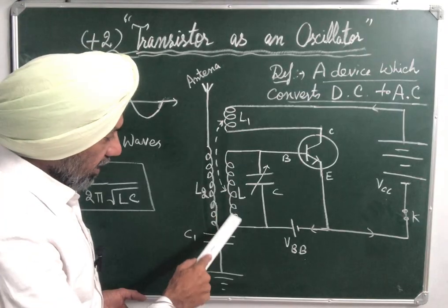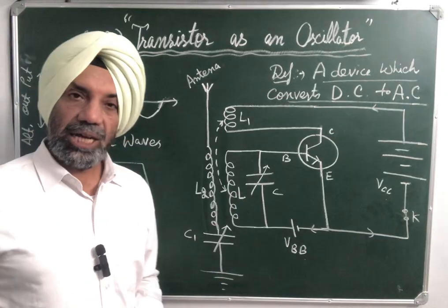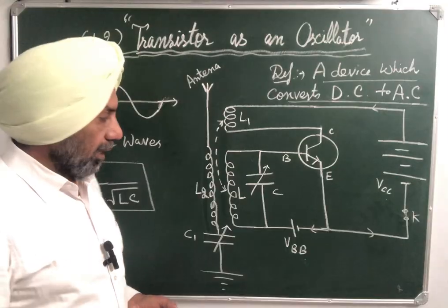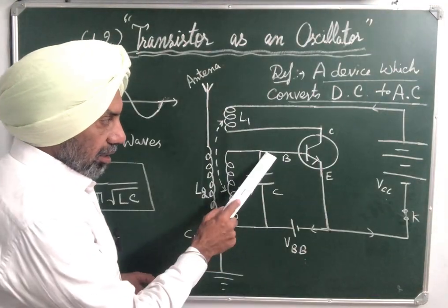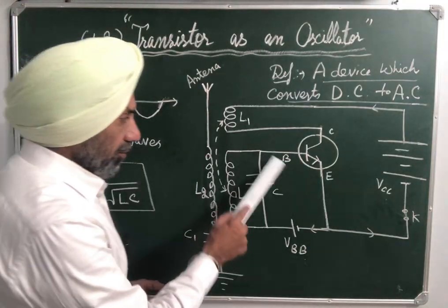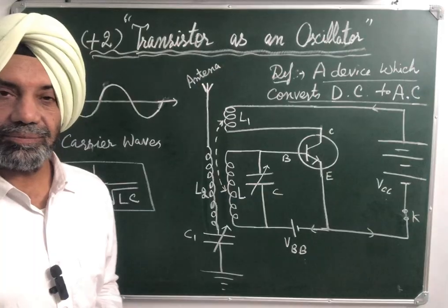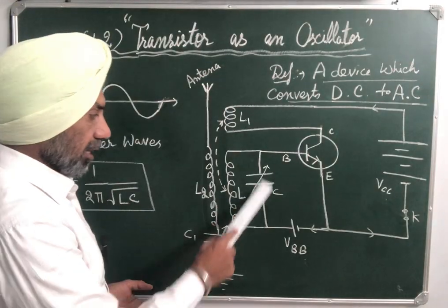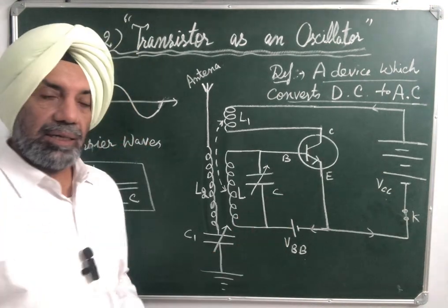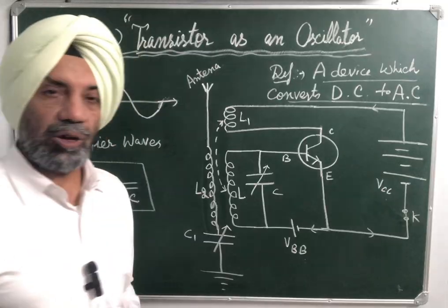When flux through L increases, this capacitor starts charging, say with the upper plate positive. When this capacitor charges, the base emitter forward bias increases, as a potential difference is set up across the capacitor. When forward bias increases, emitter current increases, which in turn increases the collector current in the outer circuit.